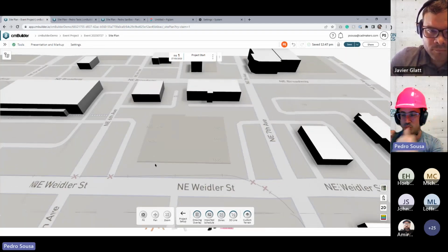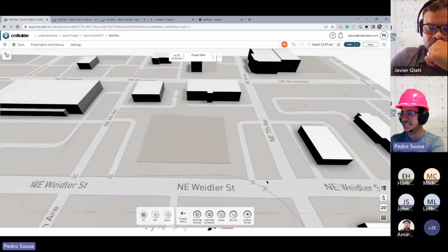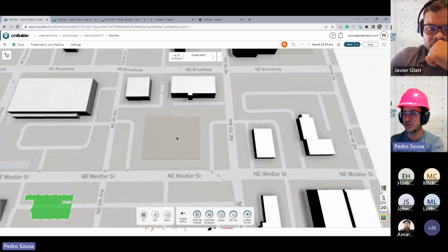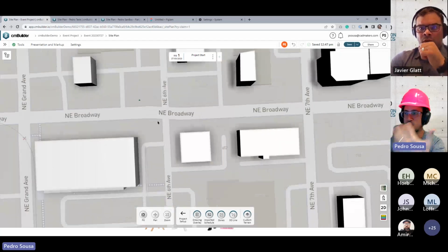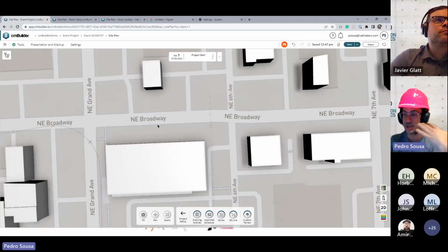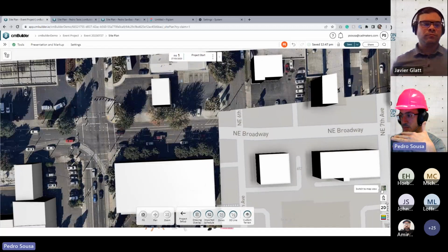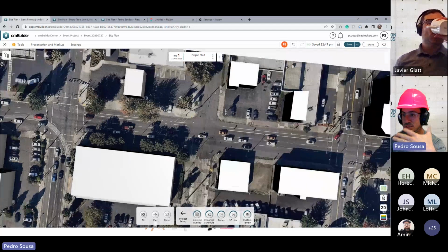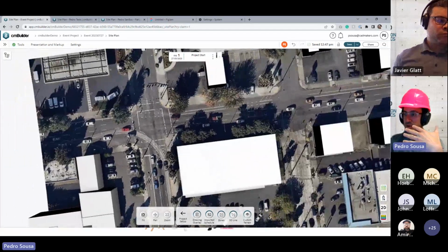And one thing that is super important, and I cannot stress this enough, is that whenever you're doing a drawing overlay, don't use this background image, because it shows an approximation of where the streets are and their names, but the sizes of the streets are quite different from the actual satellite image. So look at the street over here, for example, the one that goes north-south.